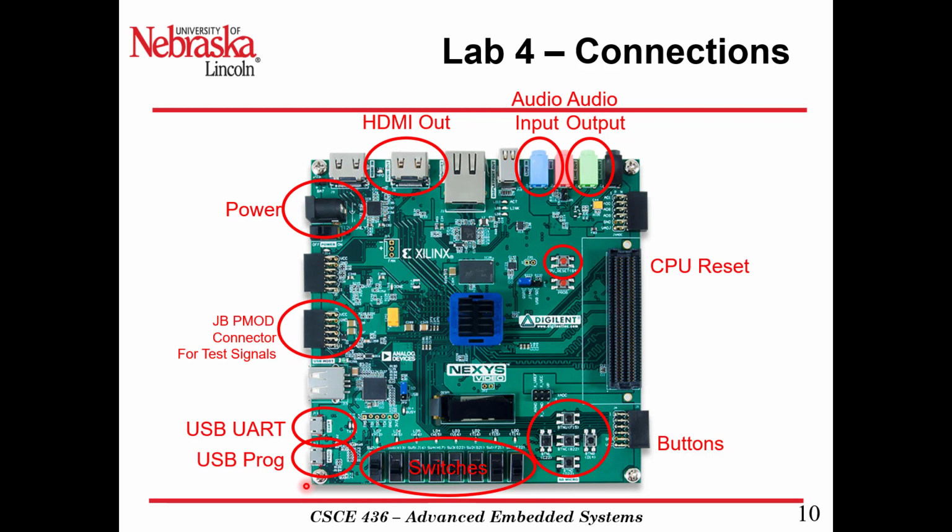There is no HDMI, but maybe later you might use your UART along with the MicroBlaze if you do the A functionality. So you're going to do a Q2.6 fixed point increment for your phase, and then you're going to have the buttons. We're going to talk about those in a bit. Those are going to be used to increase your amplitude and then change your frequency.